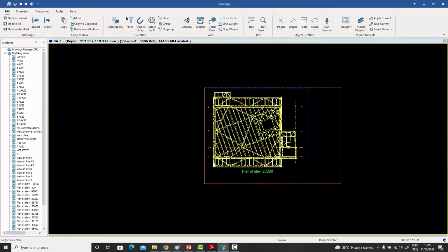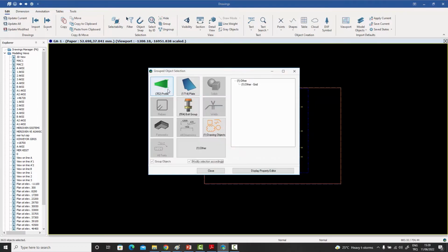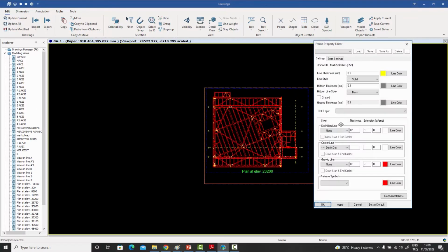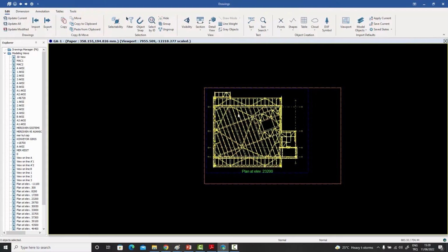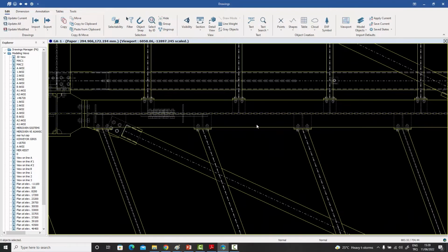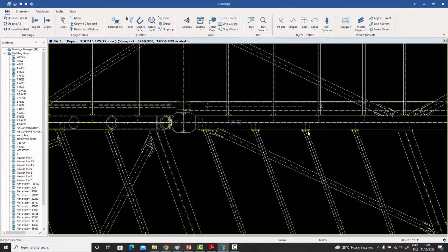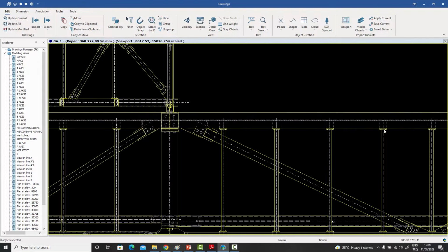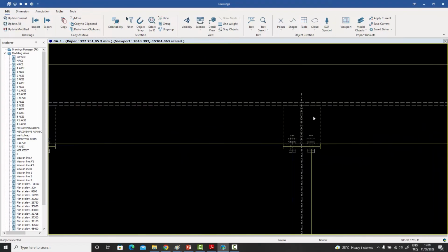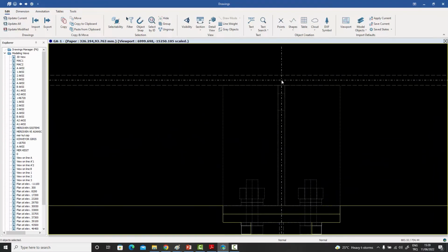So let me go back in there, select everything, do the on-the-fly filtering, go in there, convert this back to 0.1, which was a mistake, and convert all these into, say, 7 millimeters, and say OK. And when I do that now, all my center lines have been entered, as you can see over there. And now you can even snap to the intersection points of these center lines.